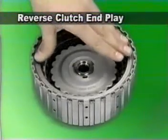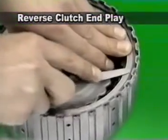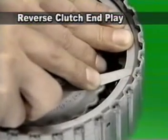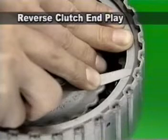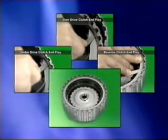Reverse clutch is measured with the thickness gauge as the reaction plate is pressed with approximately 5 kilogram force by hand. If the measured value exceeds the specification, change the snap ring with one of the 10 different snap rings. The measurement and the adjustment of the end play of the disc and plate have been explained so far.